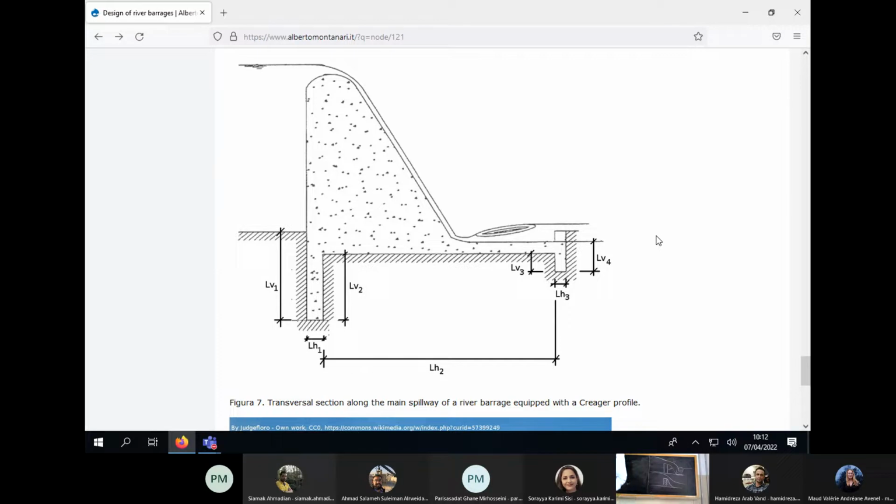So you may have water infiltrating upstream, passing by the structure in the underground and emerging downstream. This is extremely dangerous because when you have a water flow in a loose soil under a structure, then this flow tends to increase until the structure is flown downstream.